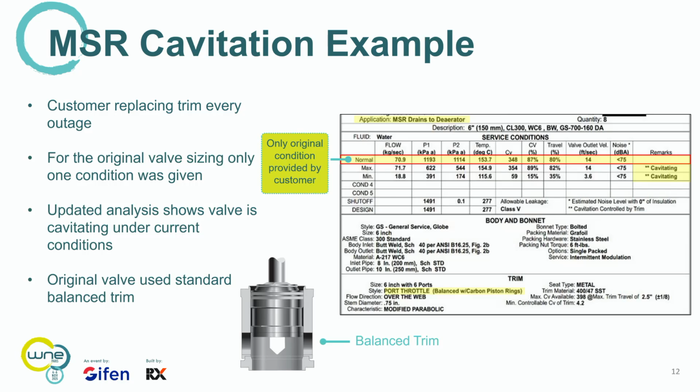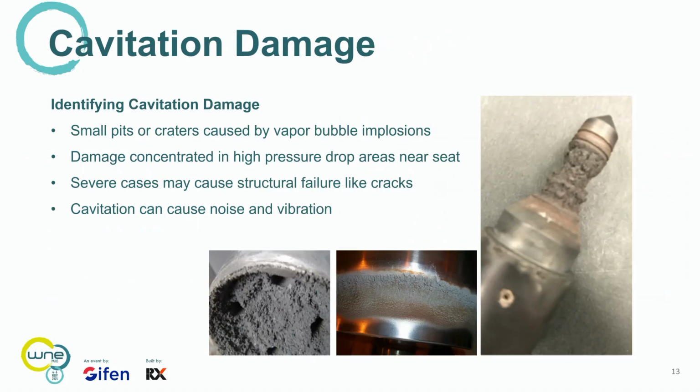Okay, so that's very key, whether you're building a new power plant or upgrading plants, to understand all the proper conditions the valve needs to operate under. Damage from cavitation is very severe, okay? That impingement, I don't care what material you make it out of. You can make it out of the hardest material. You can make it out of stellite, unobtainium, whatever you want to come up with, cavitation is going to damage